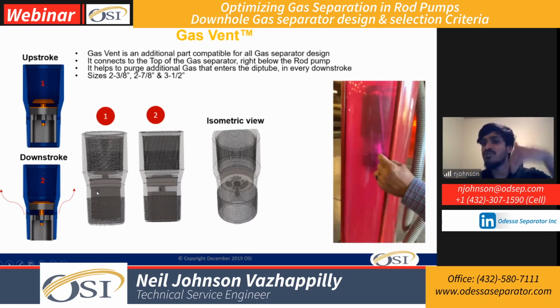So in every downstroke of the rod pump, the valve pretty much opens up because of the pressure exerted by the gas inside of the dip tube. And it opens up a pathway for that gas to liberate or escape out of the dip tube before it goes to the pump in the upstroke.